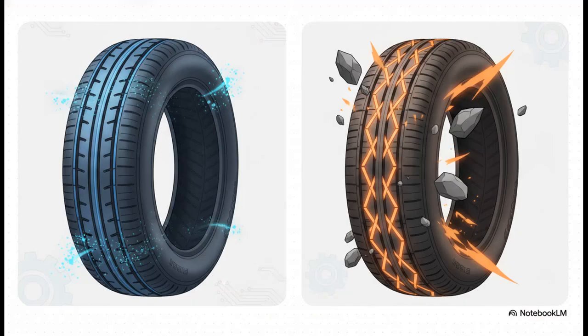Now, OTR tire size formatting might actually look a lot like your standard car tire at first glance, but a single symbol changes absolutely everything. If you spot the letter R on the sidewall, you are looking at a radial tire, and that indicates a steel structure inside. Radials run cool, they give you way longer tread life, much better fuel efficiency, and they keep heat generation really low.